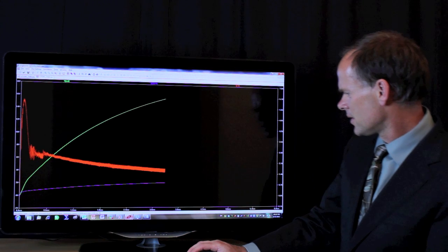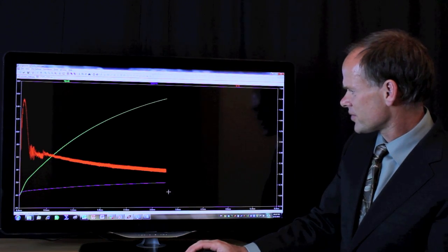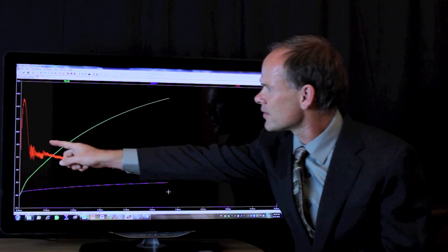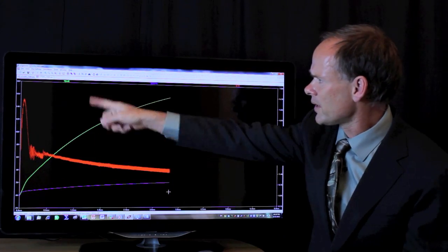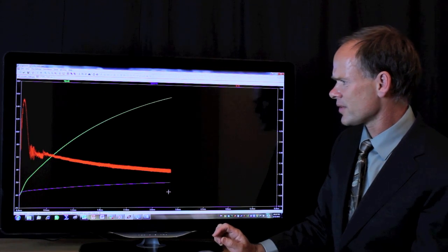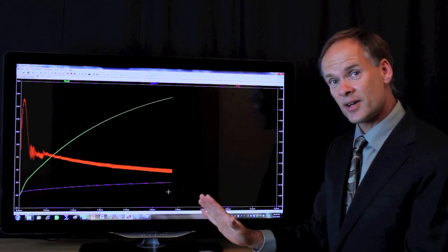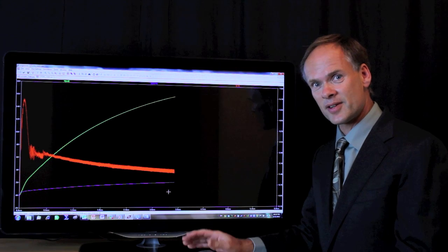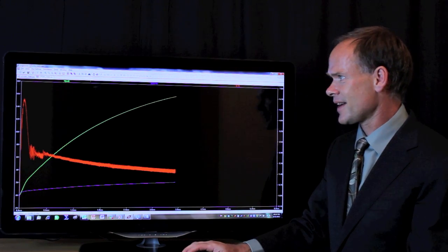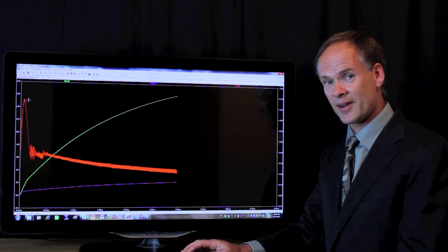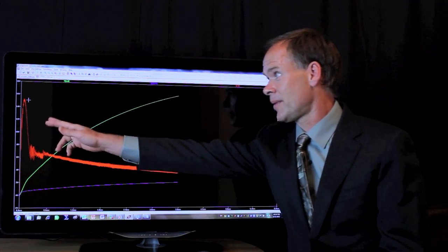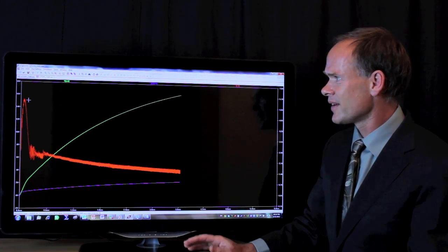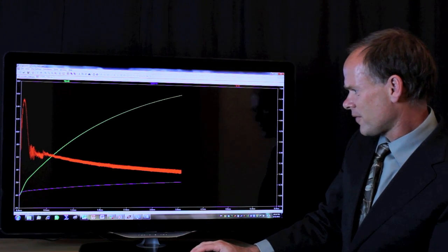And we'll do some other things in a few minutes, but let's go have a quick check on LT Spice, see how it's doing. And we're up to 3.6 milliseconds here. And there's interesting things happening in LT Spice. You see that initial current surge there, way higher than the actual steady state current that we want to see in this converter. And again, it's not clear what's causing that. It could be the parameters weren't put in properly for the controller, or maybe this converter hasn't been designed very well and it truly does have this much surge. But as an experienced power supply designer, I certainly wouldn't want that to happen in my converter, because that's extra stress on the switch. That'll lead to premature failures.